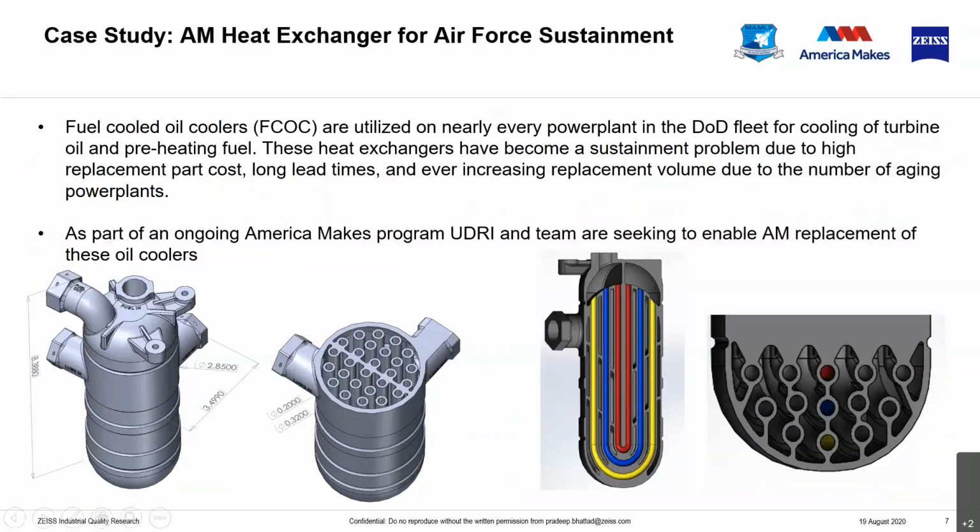So what we're looking at is a fuel-cooled oil cooler. It's a heat exchanger. The most difficult part about this part was that the replacement cost is too high and lead times are long, because manufacturing this part in the traditional manner would take a long time. And since the replacement volumes required are fairly low, nobody would set up a different manufacturing process for this. Additive manufacturing works quite well because the part is complex to make and we require them in lower volumes.